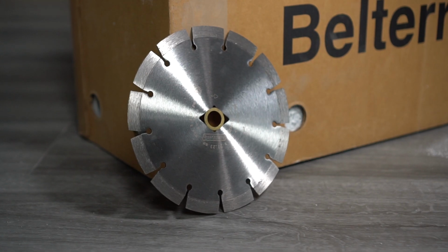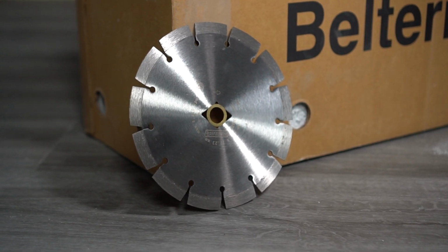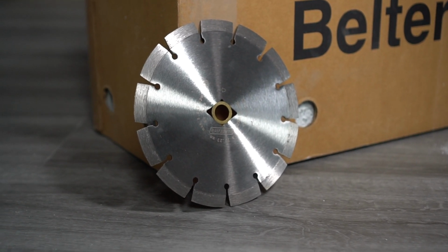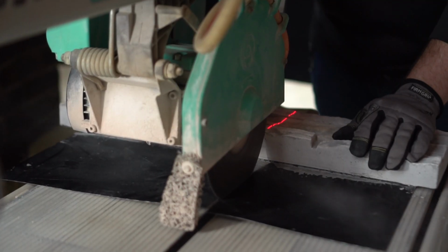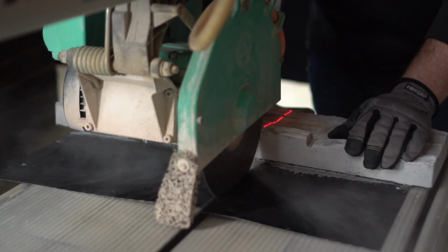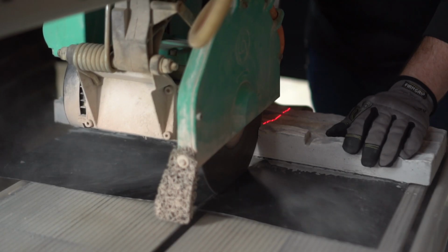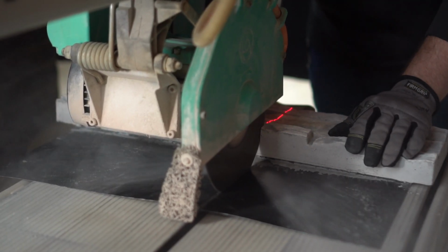Continuous rim or segmented rim diamond blades are recommended for cutting Silvermine Stone. Panel cuts should be marked and panels should be cut face up on a table saw, chop saw, or other circular style saws. Wet saws may be used for cutting to help minimize airborne dust. The water from the wet saw should be changed frequently or drawn from a separate source, so the dirty water is not recirculated, as this can cause the face of the stone to be dirty. Silvermine Stone is a manufactured stone veneer.